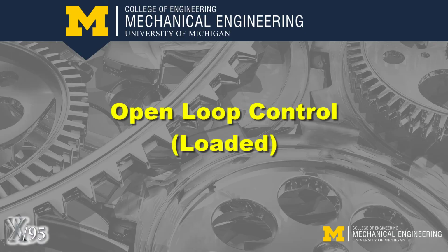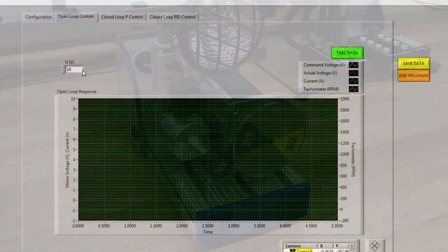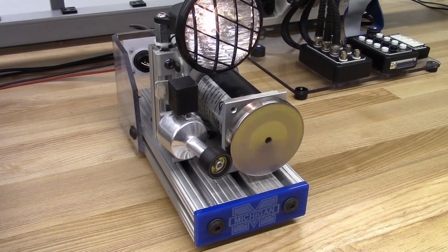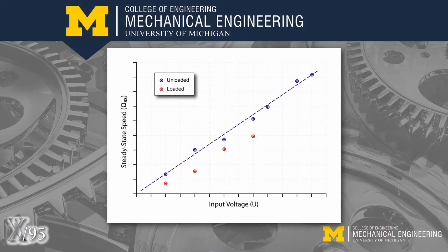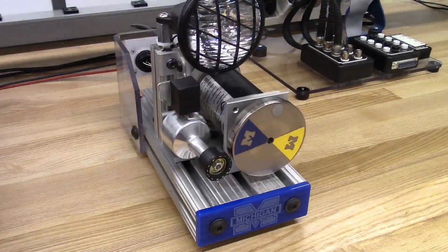Let's take a look at the open loop response when the load changes. Flip the lever to engage the bicycle generator and light. Now repeat all the previous tests to determine the open loop system gain under loaded conditions. When finished, gently retract the generator.